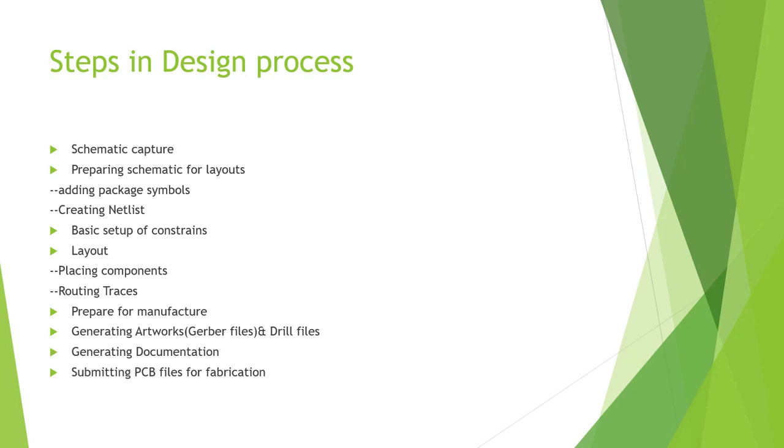That is called the Gerber file, and there is also one attachment called a drill file that should be attached to the Gerber file. These two pieces of information we send to the manufacturer, and they create the board. The last step is generating documentation.